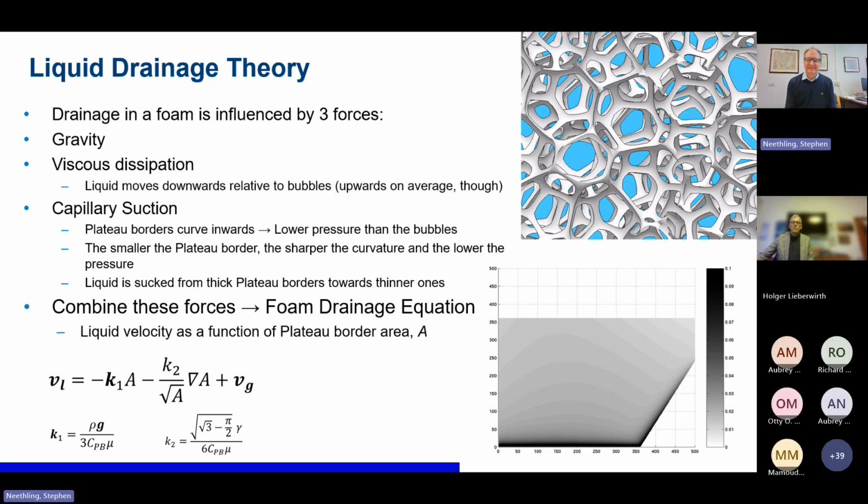But I suppose the most interesting of them is probably how the liquid moves in the system. And in terms of how the particles subsequently move, it's really the key factor in the particle motion as well, particularly the motion of the particles that are not attached to the bubbles. And you might think that that's only the gangue, but actually by the time the froth is overflowing the lip of the cell, in most of the measurements we do, over 90% of the particles are no longer attached.